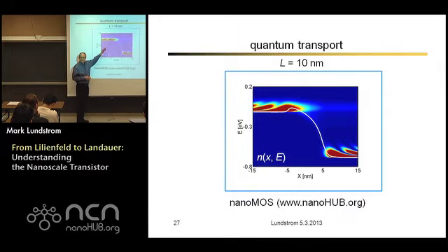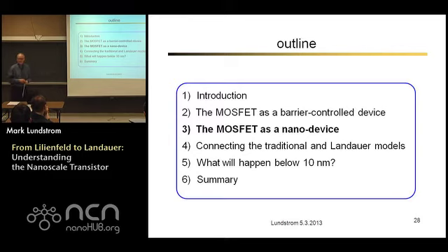You're seeing some of them tunnel underneath the barrier now. That's bad. We're supposed to be turning devices on and off with the barrier. If they can tunnel right through the barrier, it's going to make it hard. You can see some of them reflecting, and we're setting up interference patterns. This is going to be the big challenge below 10 nanometers. Can you still make useful transistors when quantum mechanics says everything wants to tunnel right from the source to the drain? But for 10 nanometers or above, we can think about this classically, and it's pretty easy to understand.